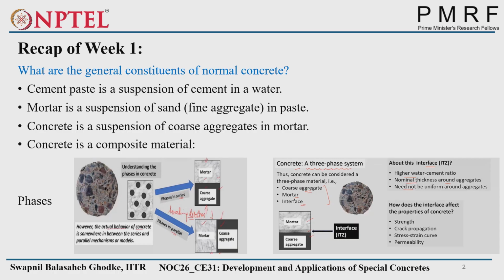Sometimes, like in ultra high performance concrete, we use a filler such as quartz powder, which is an inert material that will not react with the water like a binding material, and will only fill whatever gaps or voids there are between the gradation.